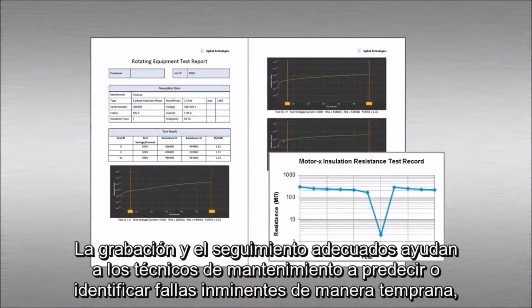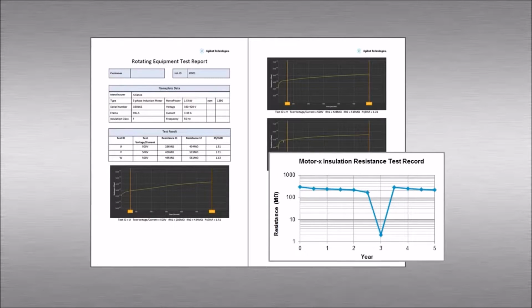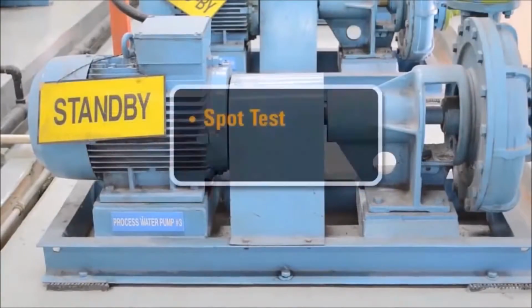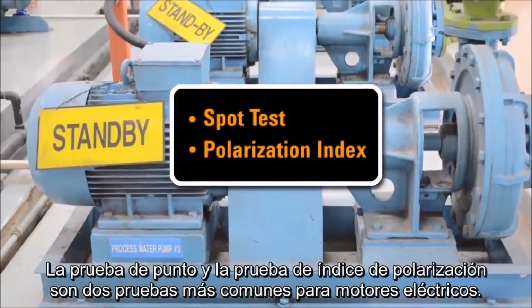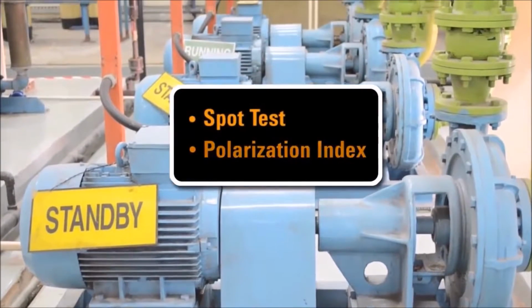Proper recordings and tracking help maintenance technicians predict or identify imminent failures early, before they result in costly unplanned downtime due to motor failure. The spot test and the polarization index test are the two most common tests for electric motors.